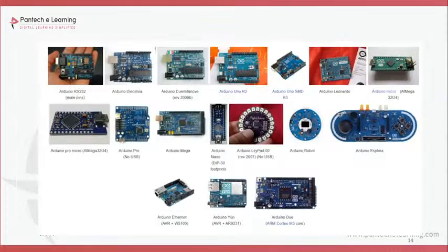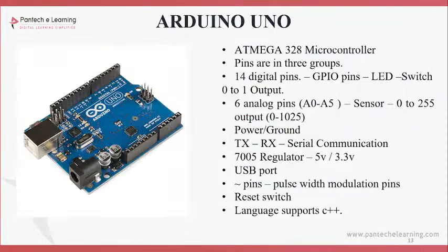Okay, I have explained what pins are available and how they are working. Like that, I have explained what type of protocol we can use. Using this microcontroller, we can use the UART protocol, SPI, I2C. These three protocols are the major protocols we can use. After that, protocols like RS232 and RS485 can also be implemented.